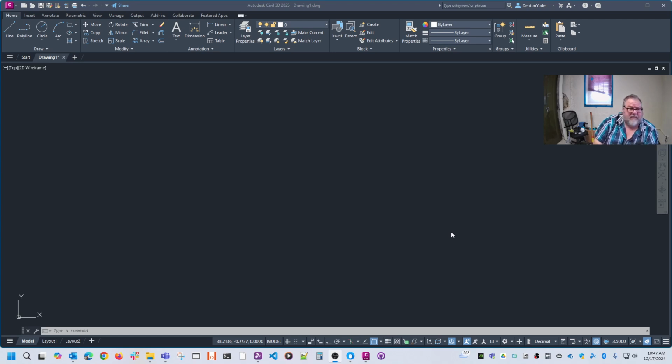When we make blocks, there is a block command which makes a block definition inside your drawing. I never ever use that because I see it as a waste. I go straight to the wblock command. The wblock command will create a block, but also write it out to the hard drive as a drawing. And so the way I teach it, blocks are really just little tiny drawings.